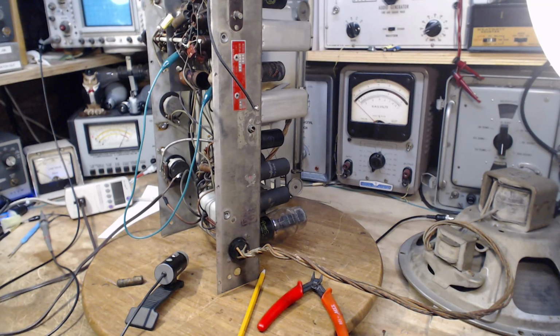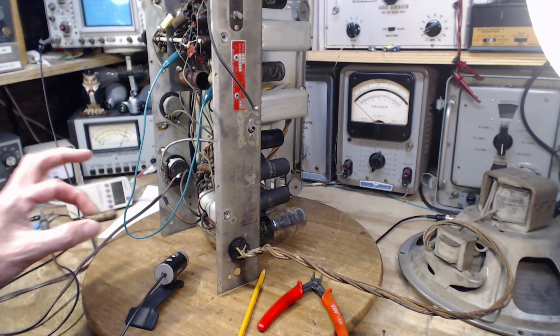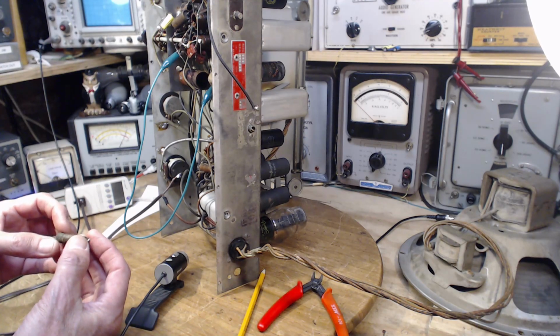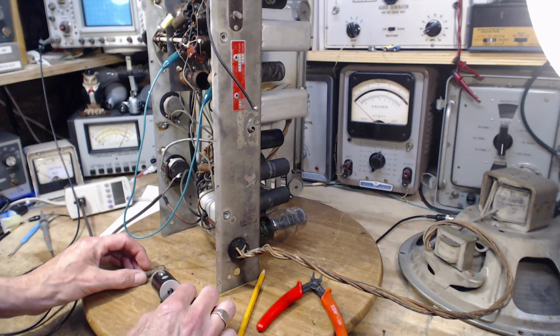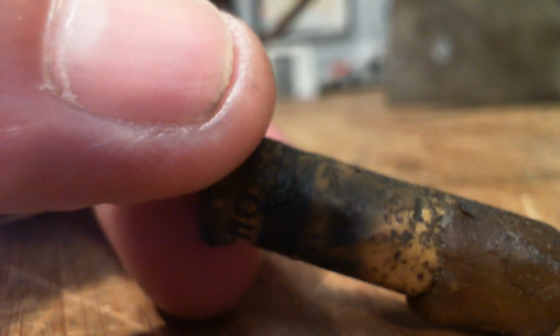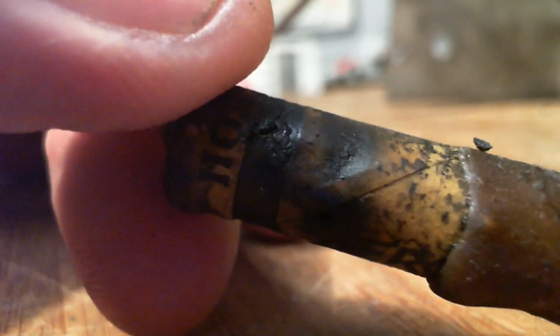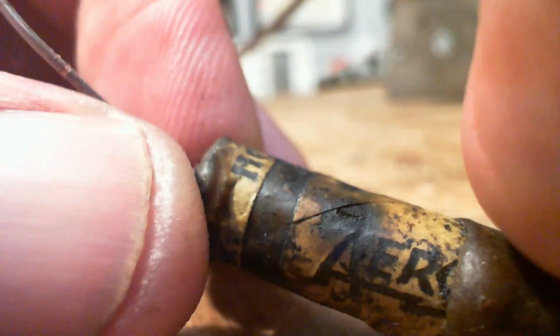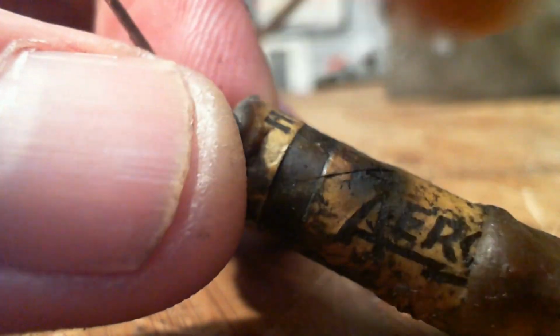Okay, so I thought it might be interesting to know exactly where this capacitor is in the radio circuit. So I figured that out. It took quite a while. I'm just going to go through all the steps here. So first we're going to look at the capacitor and see its size. This looks like a 0.01 to me. When you look at this egregious mess here, well, you can really see the burns in it now. Look at that. And the wax is completely gone from here.